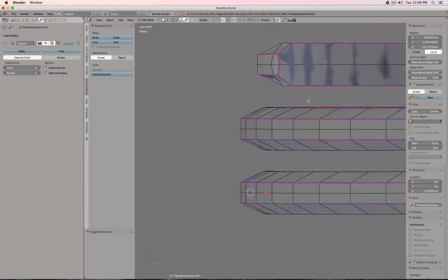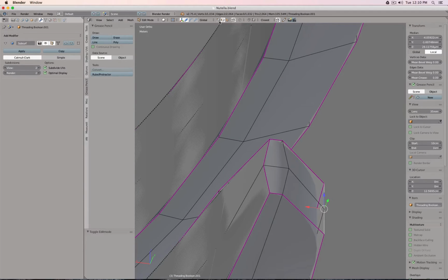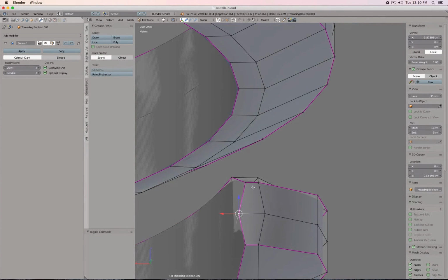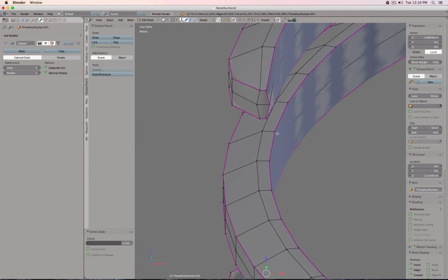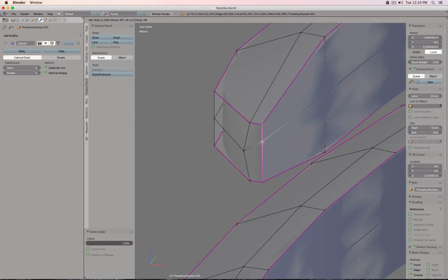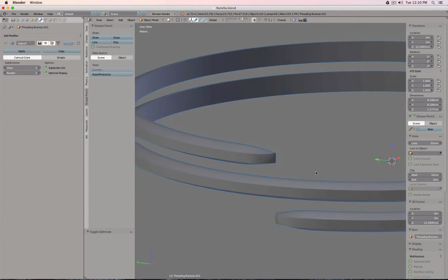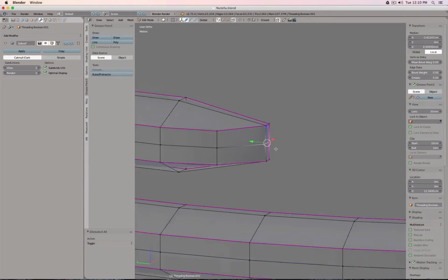Also not bad. Okay. What happened to this point here? This shouldn't have happened actually. So I would like to get this one to the midpoint between them. A little bit tricky, but not really. So GG. Slide back to this edge. Now you see this line is straight. GG to the midpoint is actually 0.5. Done. Let's do this here one more time. So I slide it with GG to an end. GG along this edge 0.5 to the midpoint. And cleaned up. And now I have this midpoint here at the center.